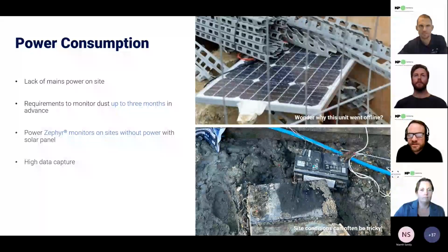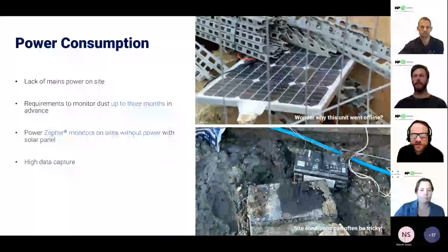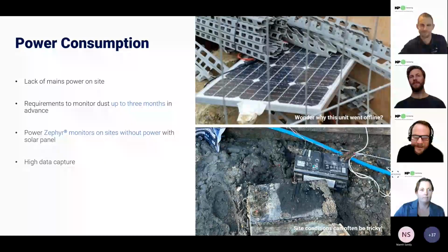We also recently tried to run these legacy monitors off batteries. We were using 2 marine batteries linked together, approximately 250 amp hours each, and weighing around 65 kilograms each. These batteries still needed to be swapped every 2 to 3 days. The poor guy who had to do these swaps on site was no spring chicken, and he was glad to see the back of them.